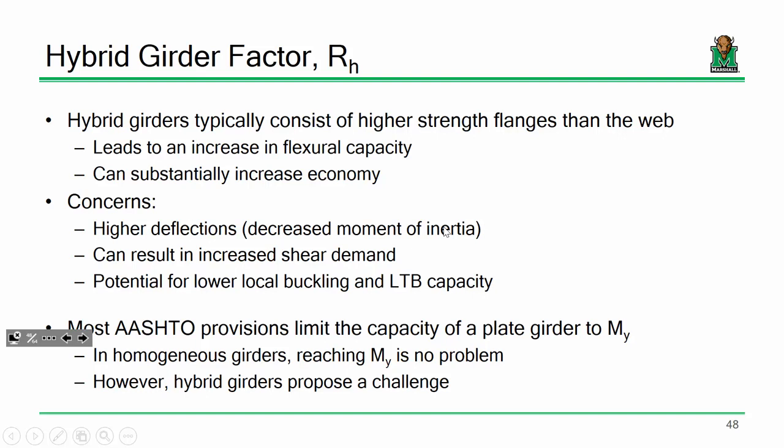When we design those types of beams, we usually like to take the best species of woods, the ones with the most advantageous properties, and put them on the top and bottom. And for lack of a better term, the trash wood, I don't really want to say it's trash because it is an engineered product, but the lower grades of wood we put in the middle, because the middle isn't really seeing the high bending stresses. Sigma equals My over I, the highest bending stresses are on the top and bottom. So put your best wood on the top and bottom.